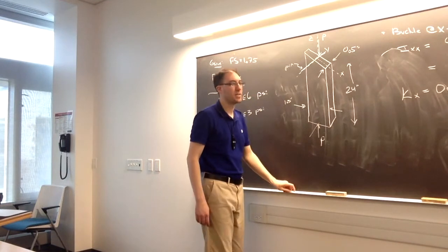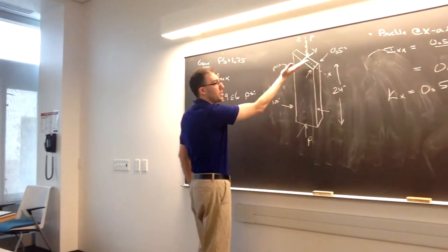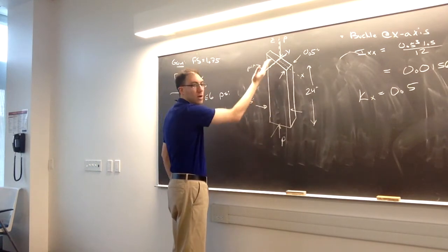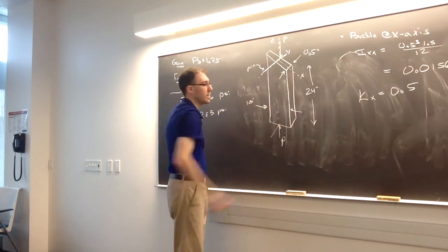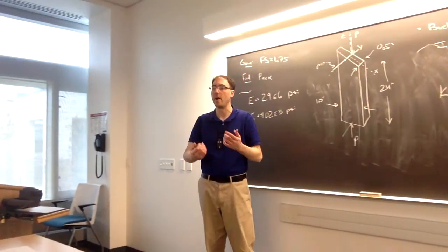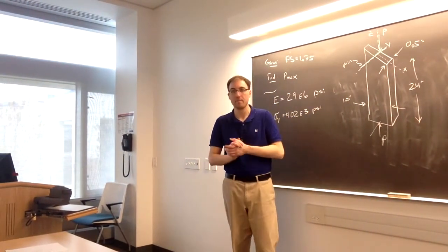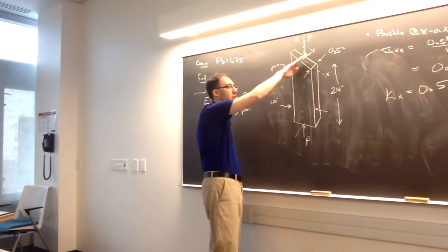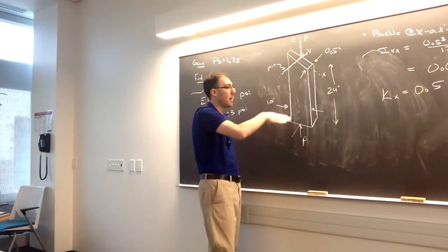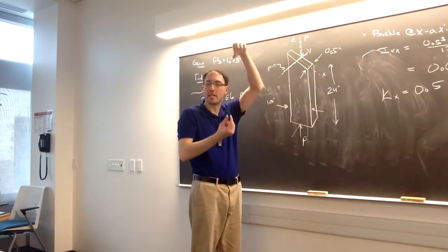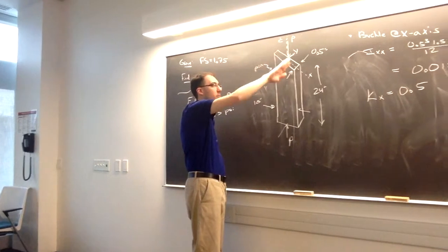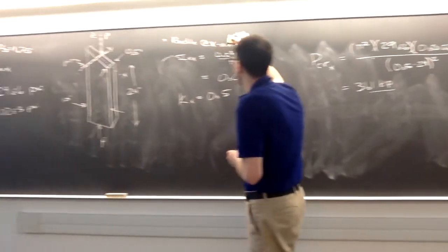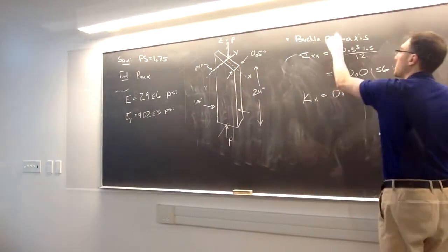So in this case, it's a little tough to see. If it were to buckle this way, it's going to bow out around the x-axis, either along this direction or along this direction. And that's how it's going to fail in that mode of buckling. What we also would consider is, what if it buckled around the y-axis? So it actually bows out this way or bows out that way. And in this case, the top and the bottom are free to rotate around that pin connection for it to fail. Right, so also we want to check then, what does it take around the y-axis?